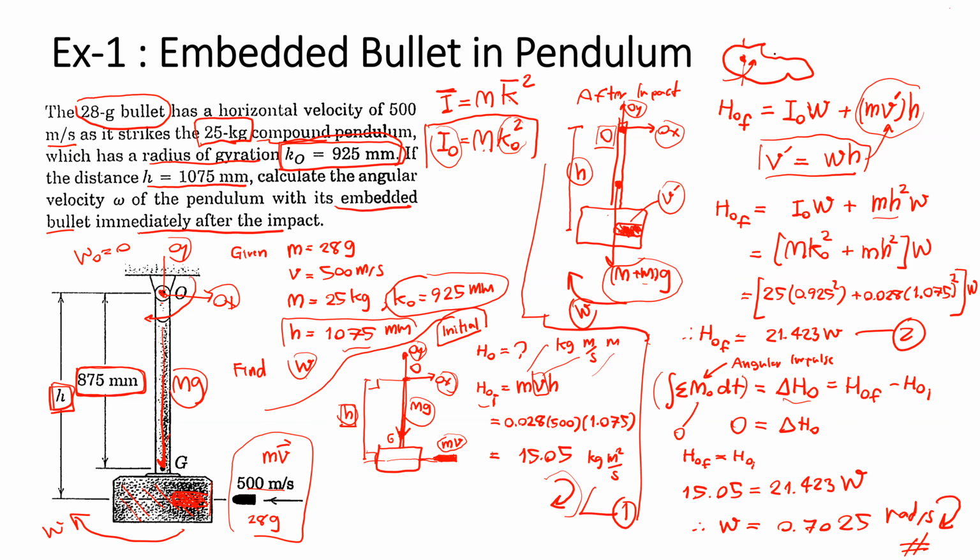In the experiment, you may mount the robot arm with a rotational actuator and try to rotate. When you know the torque, and you can measure the angular acceleration, you have one blank thing here. And this one blank thing should be the moment of inertia about the rotational axis.